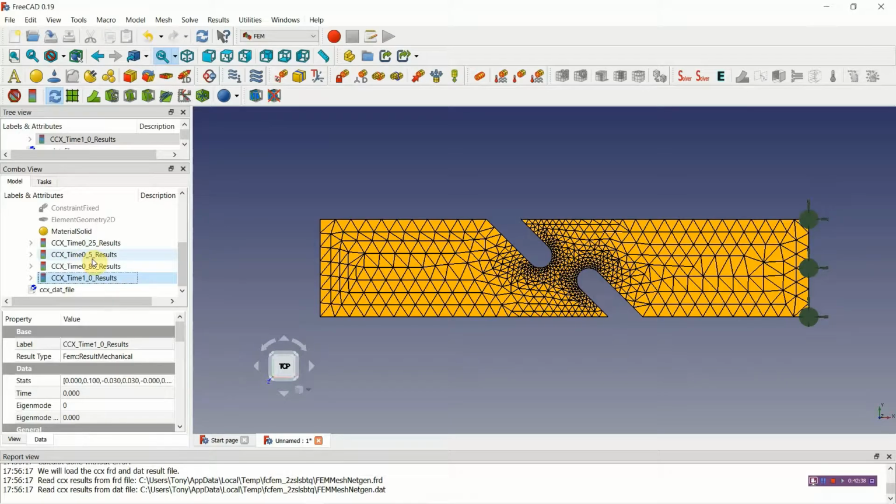This is something that all of these codes tend to do. It's not a dynamic transient analysis where time is really involved. It just uses time as a means of saying how far we are moving through the analysis. So time 0 means a start and time 1 means an end, but it's not a physical time of 1 second.